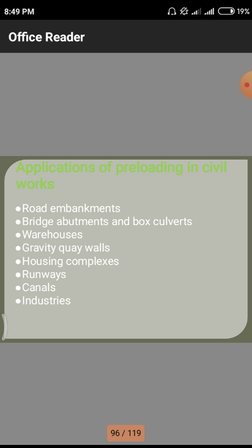Next one, we have canals. Normally we employ canals with mud works. That means sloping is provided on the canals in trapezoidal patterns. Why? Because a trapezoidal pattern has a huge capacity for water to travel along the canals, so canals normally use trapezoidal patterns for transferring water from dams and other huge water structures to the fields.